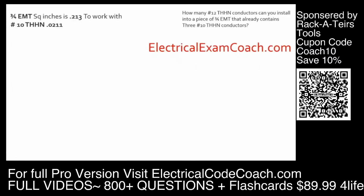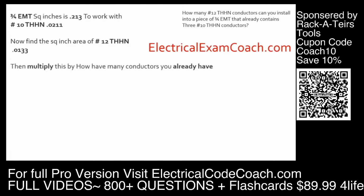Now that we have our conduit and our starting conductor, let's go ahead and write down our number 12s. That's the conductor that we want to install. Then we'll be done with the code book, and all we have to do is some simple math. After we find that value and write it down, we can proceed. We multiply the conductors that we already have. We have 3 number 10s multiplied by the value for a number 10, and that gives us this number.